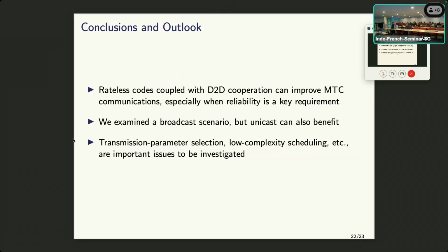So all this initial work shows that yes, in terms of latency reduction of firmware updates and ensuring reliability, fountain codes or rateless codes indeed have the potential to accomplish what we want. The issue, of course, is computational complexity. That needs to be tackled, how we can best handle that. Of course, linear time encoding and decoding methods for Raptor codes are available. So that is one ray of hope.